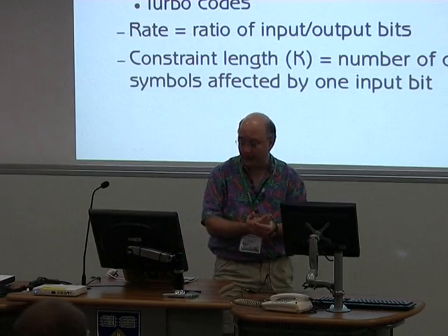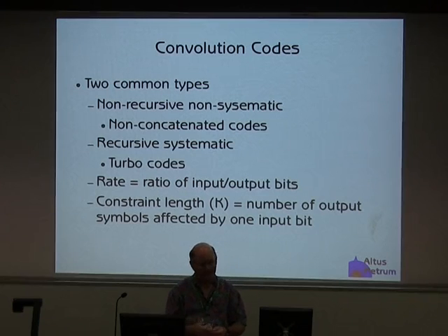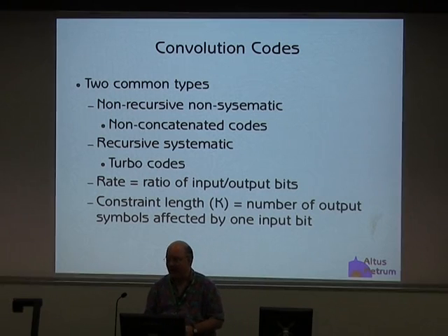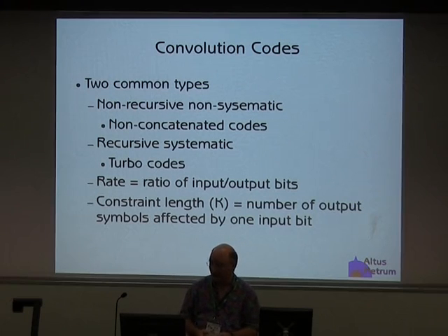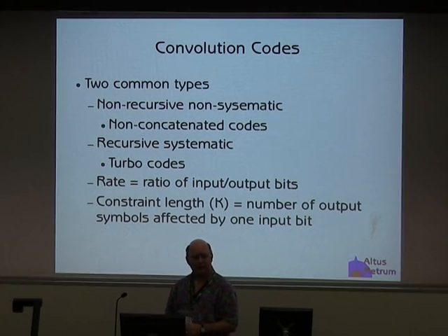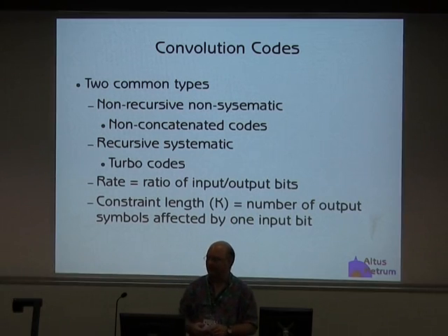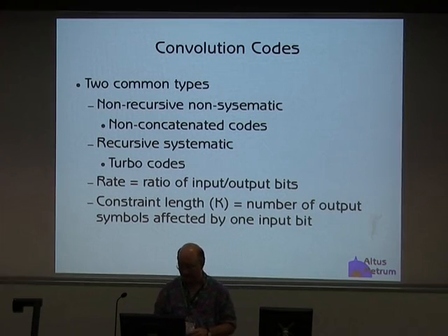Convolution coding is what I've done. That's because it's what the CC11 did, and what the CC1120 does not do. There are two common kinds of convolution codes, the non-recursive, non-systematic codes and the recursive systematic codes. A systematic convolution code is one which replicates the input in some of the output bits. So if you had a perfect transmission, you could just throw away all the error correcting bits and extract the signal directly, because the original signal bits would appear in the output.